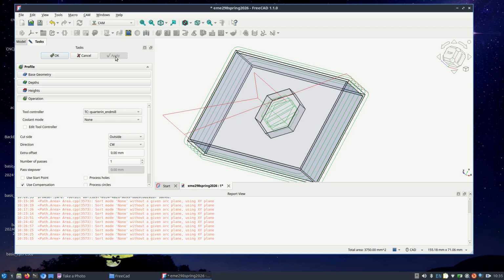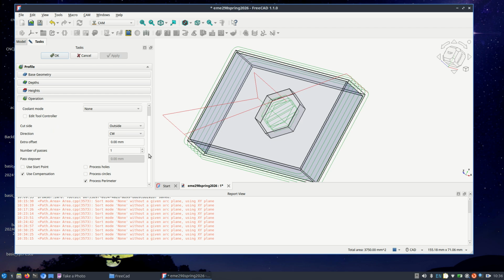Why does it cut on the top? It doesn't even take anything, it just traces it. Because we told it to start at a +3. Our first here is actually 0. We need to take the first pass at +3. So that's why it's taking one that's just flying. And why do we tell it to do that? Just because sometimes we're gonna make mistakes, and that's our insurance.